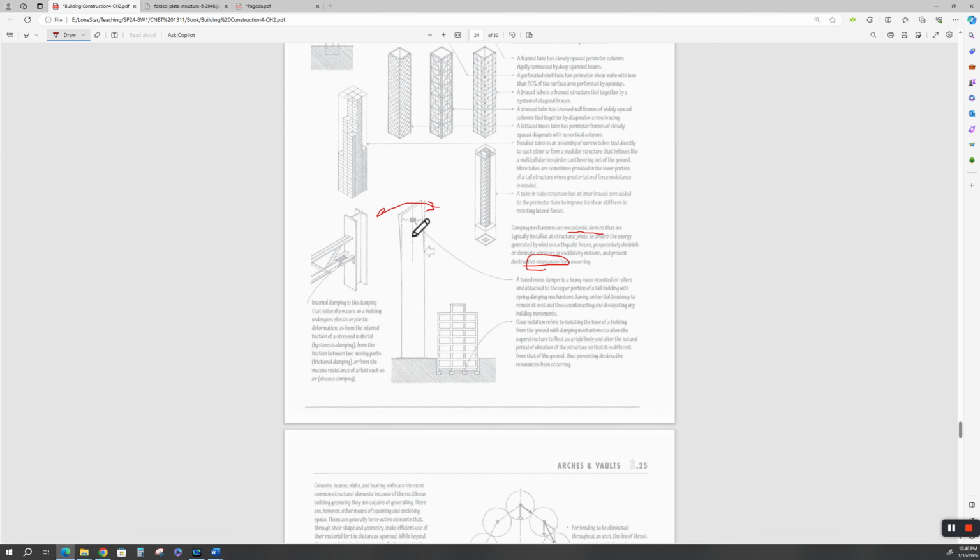And so if this thing starts to sway over here, what's the reactive force going to do? It's going to roll out from underneath the building movement. The springs will pull it back. Springs will pull this, and it goes back and forth and tries to slow it down.